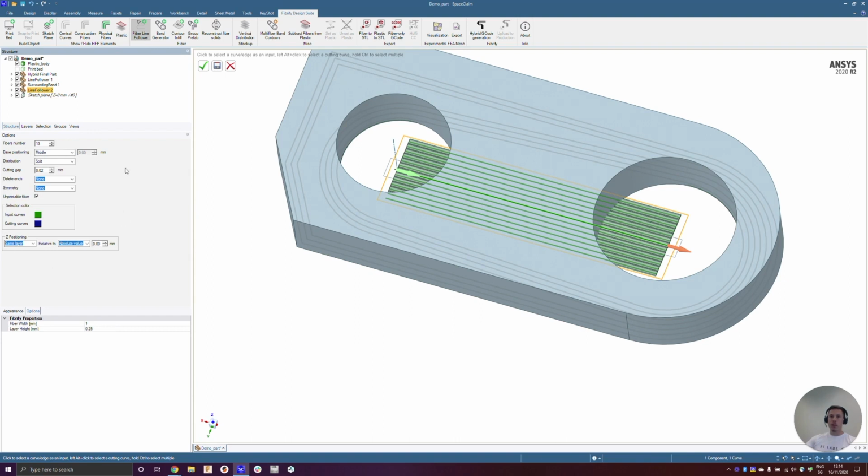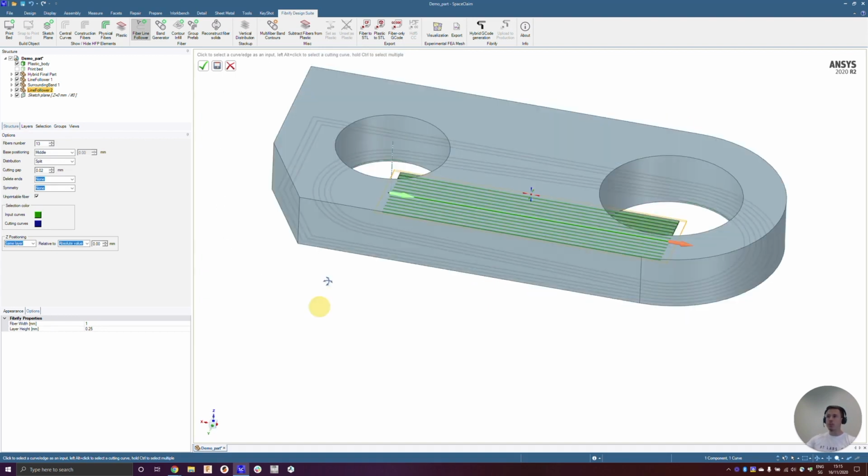The options we see now here are the ones that were used to create this line follower. And when we look again into the left top corner of our design window, we now have two options. The green check mark meaning that we can create a new prefab based on these options, and the floppy disk or save icon means that we can actually edit these options here and update the already existing line follower. And this is what we will do now.